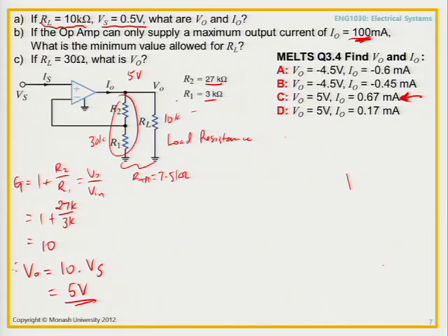You reduce that a bit further. Say this is now 100. So 1K. Let's say now this is 100 ohms. So you're starting to draw more and more current down this branch because the resistance is low. In fact, if you took this all the way to, let's just connect a short circuit here, then you would draw all the current out of the op amp through this branch.